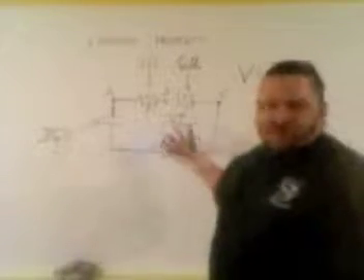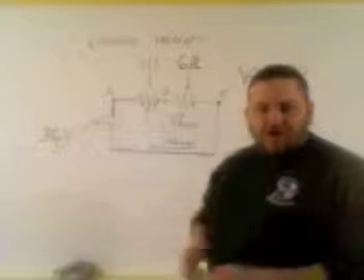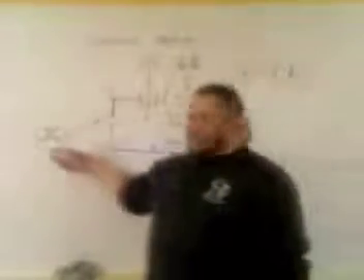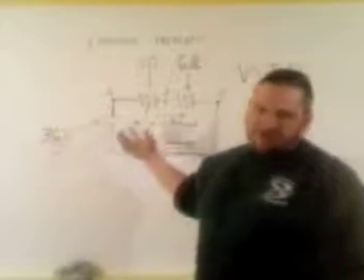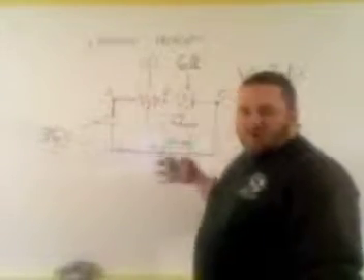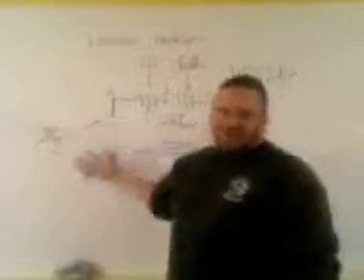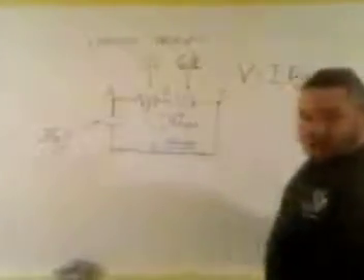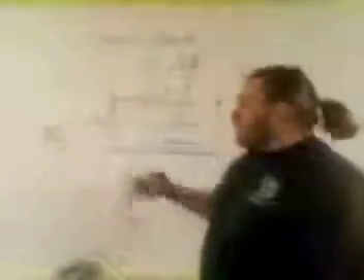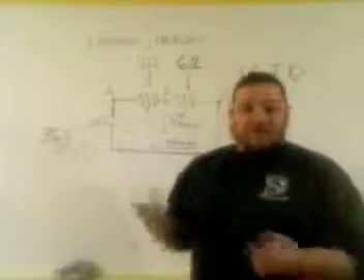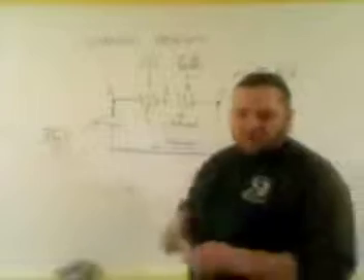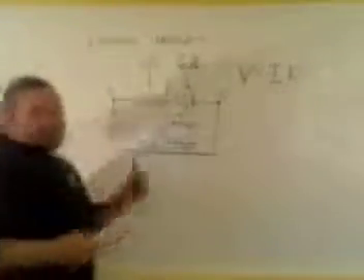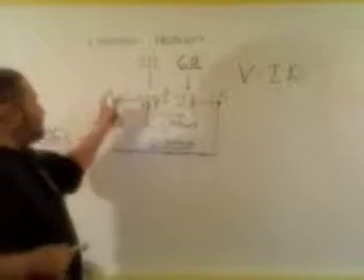Let's say you have a circuit that is relatively fragile, and you don't want 36 volts through a particular part of that circuit. Well, you put a series of resistors in front of it, and you can lower that potential so that instead of 36 volts, or in the case of a wall outlet, 120 volts, it's only experiencing maybe 10 or 5. Okay? So those are all important reasons why we use resistors in circuits.